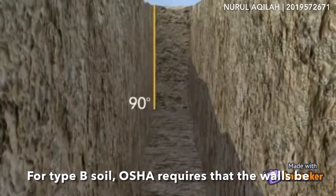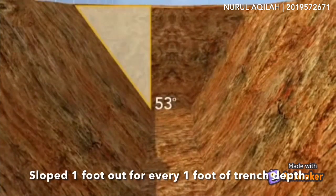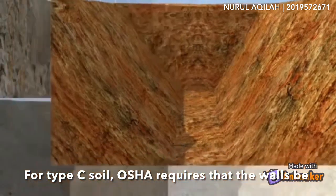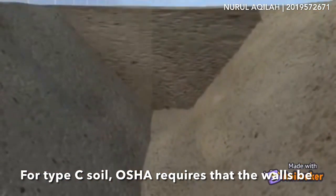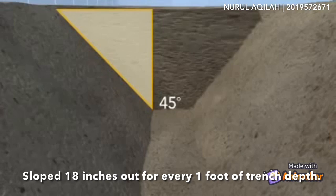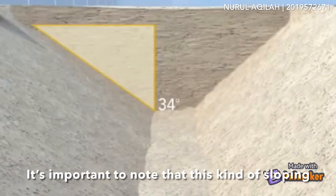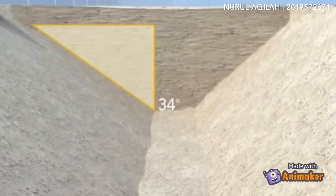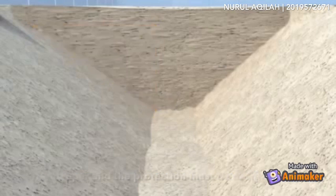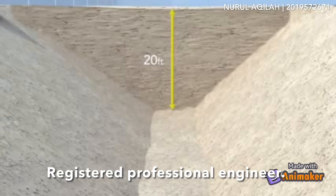For Type B soil, OSHA requires that the walls be sloped 1 foot out for every 1 foot of trench depth. For Type C soil, OSHA requires that the walls be sloped 18 inches out for every 1 foot of trench depth. It's important to note that this kind of sloping can only be used for trenches less than 20 feet deep. Any deeper and the protection must be designed by a registered professional engineer.